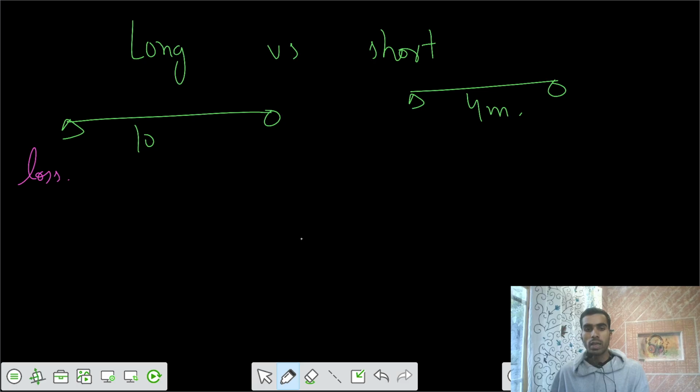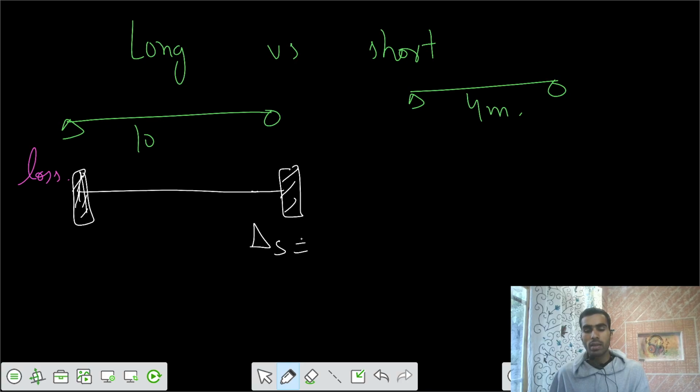Once I am fixing the steel wire from one side, and now I anchor the other side also, let's say the slip is there, and the slip is a function of the anchoring mechanism that we call the anchorage system. So your slip is a function of the anchorage system. For a particular system, that is a fixed value.